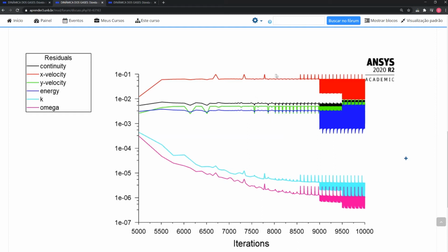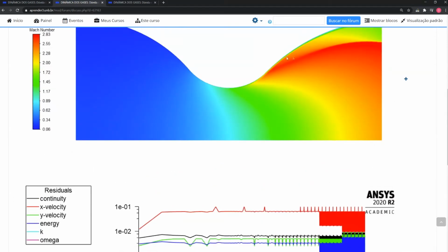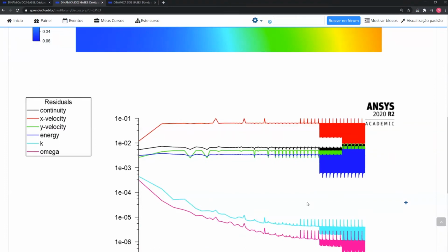In this case here, these disturbances happen when we are simulating our boundary layer. Probably there is some uncertainty because the type of the model, the type of the equation system, is changing when flow transits from supersonic to subsonic region, and this mathematical oscillation happens. It's quite visible that it's just some mathematical problem here. It's absolutely no physical problem here.